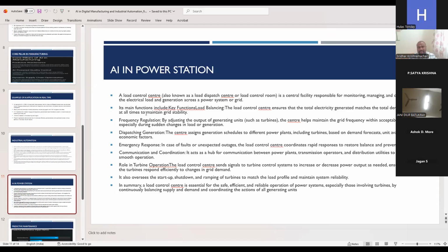Okay, I'll move forward. Whenever there is an increase or decrease in load, the frequency will get proportionally increased or decreased. For example, if the generation station sees an increase in frequency, it means some load station has had a load shed, tripped or power failure. Based on that, the RPM of the turbines, the thermal power stations, and the shut-off of solar stations will happen automatically. It's nothing manual. Even we cannot control it manually.